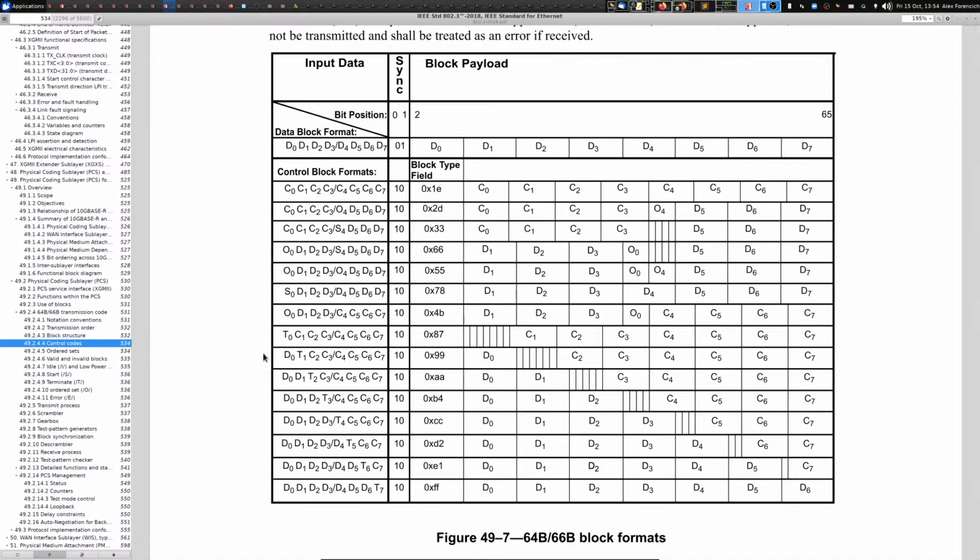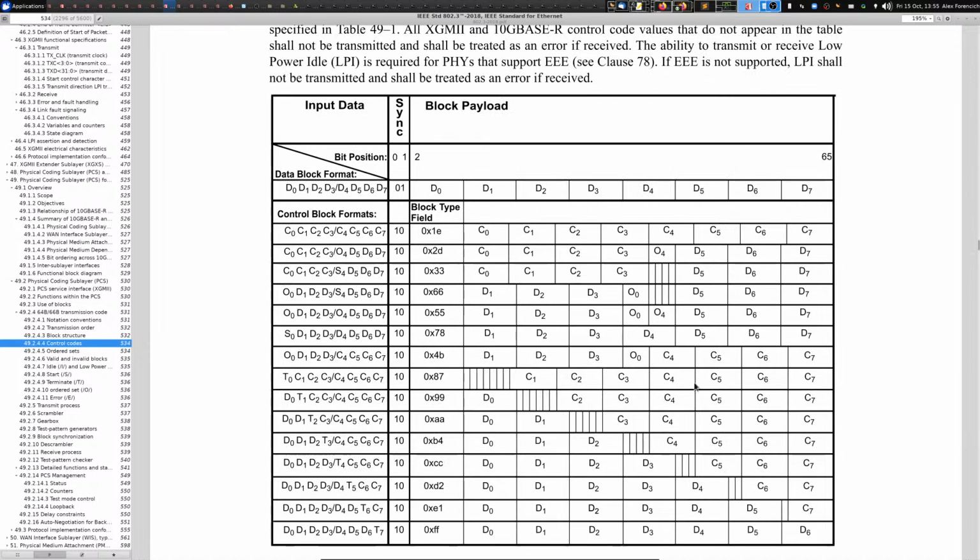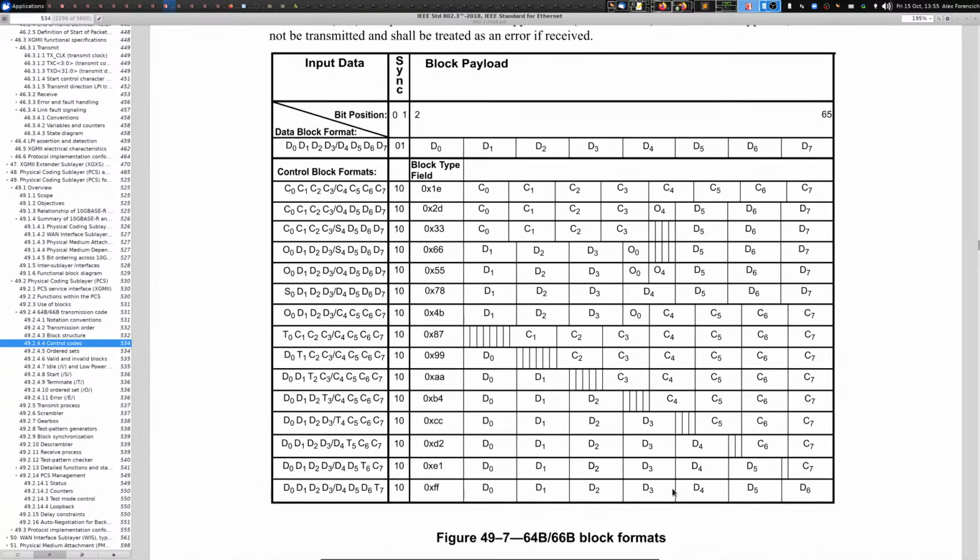So what I want to do today is look at writing a little Verilog module and potentially make some modifications to the PHY modules that will permit checking more of the on-wire format to make sure that we're seeing what we want to see, that we're seeing a valid signal. And if we aren't seeing a valid signal, then we can kick the transceiver and reset it.